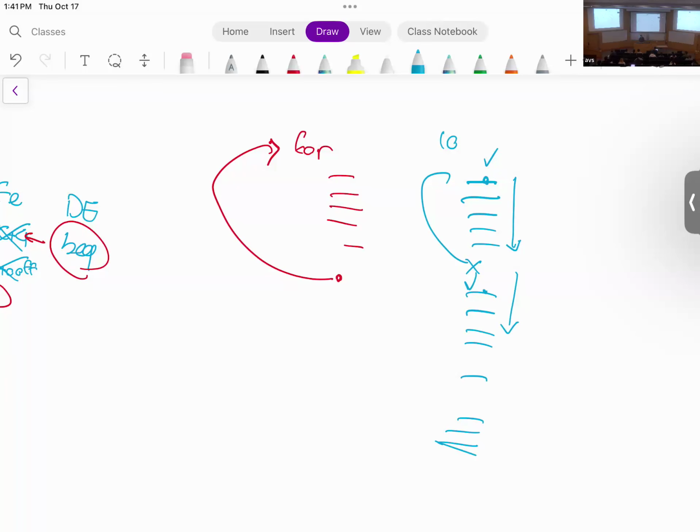The trade-off, though, is that unrolling means the size of your memory increases, because what used to be, let's say, 10 instructions that we just repeat by having a loop, now, if I unroll this 10 times, I have 100 instructions. And these 100 instructions need to be stored in my instruction memory. In the past, it was just 10 instructions and a loop counter.